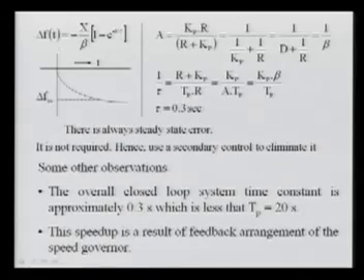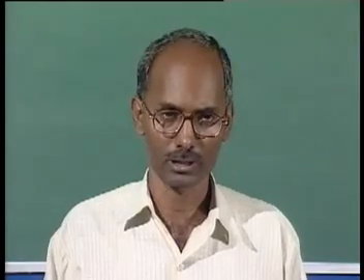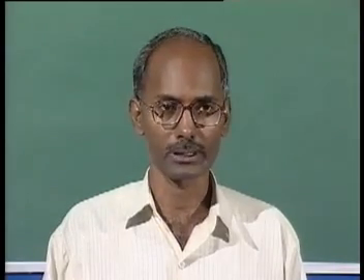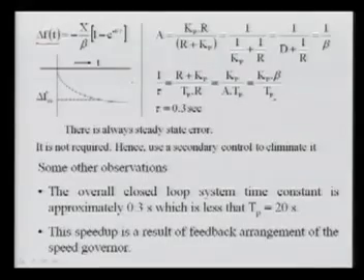So here I derived this expression of the frequency, a time varying frequency. Here we ignored the time constant of the turbine and governing system, and only considered the power system time constant, that is Tp, and then derived the simplified dynamic response. So in this frequency expression, x is the change in the load, the magnitude of the step we are talking about.